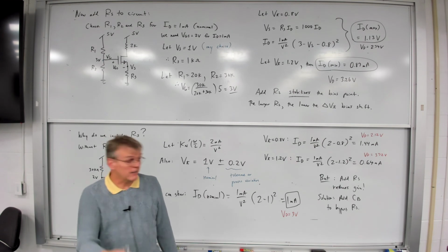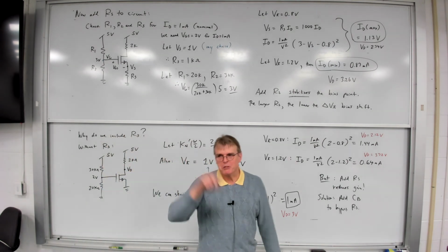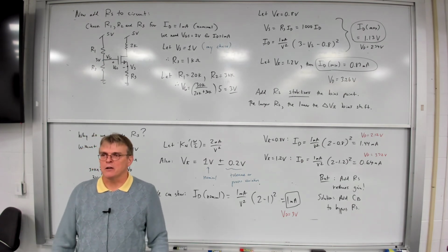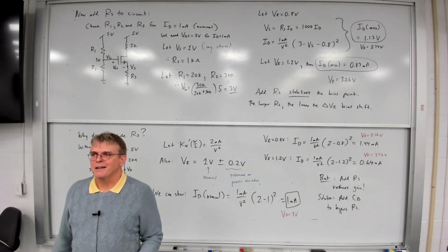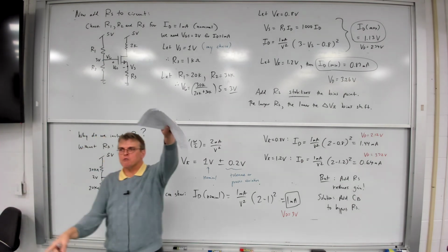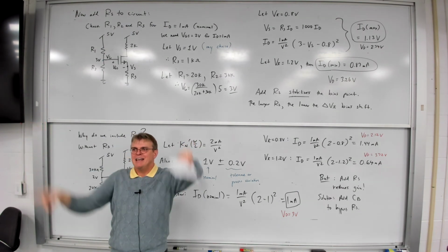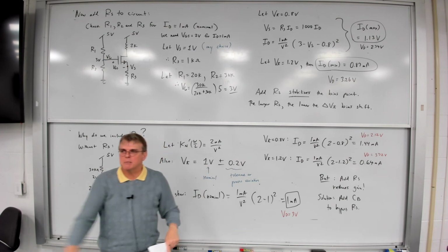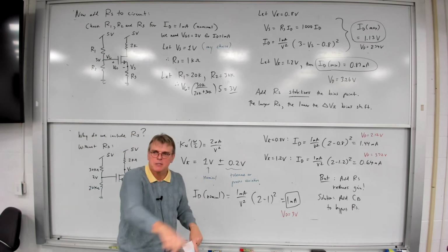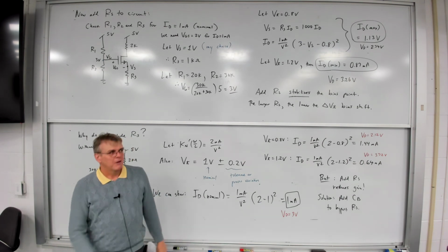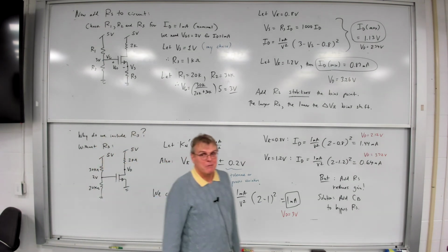Incidentally, as design engineers, guess what you're going to spend a great deal of time doing? Monte Carlo analysis. Because they will always tell you, look at the corners of the design. What do they mean by that? They mean look at the extreme operating points due to tolerance and voltage variations and everything else, and make sure over every possible operating condition and every possible tolerance you may encounter, the circuit keeps working. So that's what you spend a great deal of time doing.